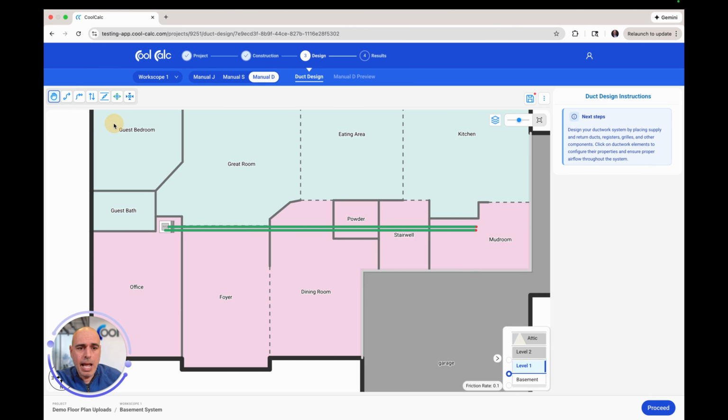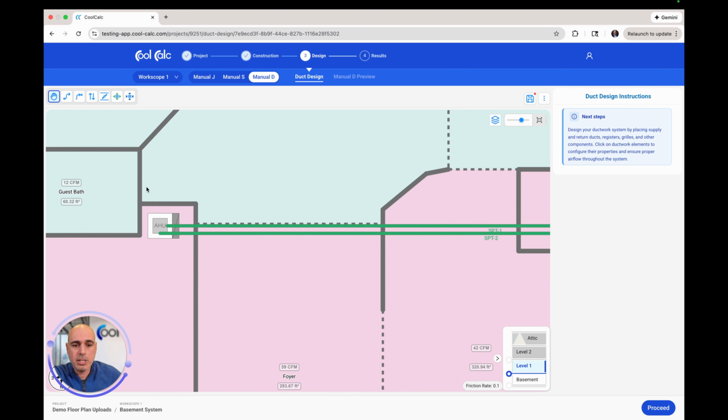We are looking at adding a shortcut in the future where when you click on supply path, you'll be able to pick single, double, triple connection, and it will make all of your trunks in parallel and do all the connections at the AHU. So it'll be quick and easy to do in that case.